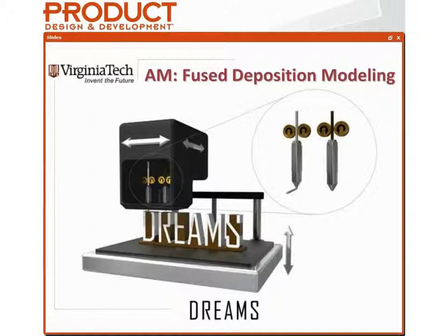In the Stratasys technology, you'll see they have two different extrusion heads. One allows it to create the build material. Here in this diagram, that's the white lettering of the word dreams. And then it also has a support material. That's the brown material. And that support material is sacrificial. It's there only to help create complex geometries, basically difficult overhangs and undercuts, since this is not a subtractive technology. It's a sacrificial material. It's water soluble on the Stratasys platform, which allows us to make some really complex shapes that really can't be made by any other means.